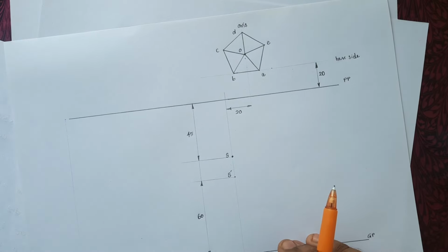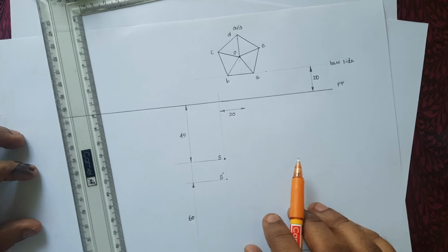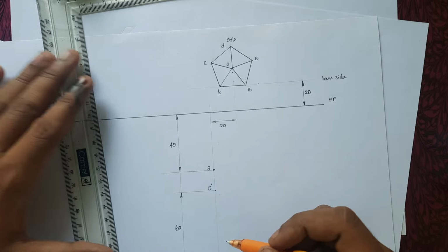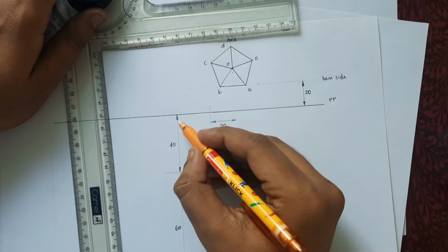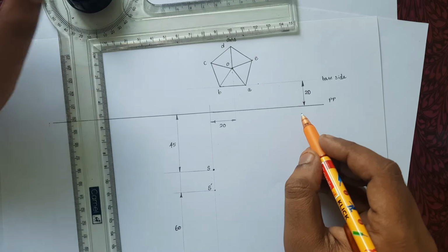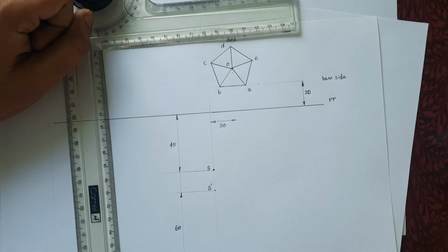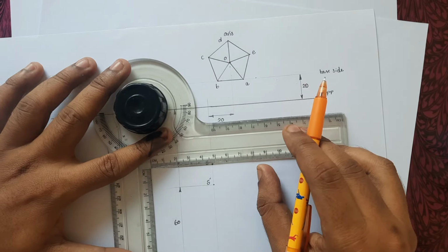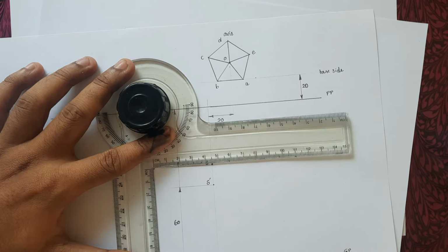Okay, clear. And now we have drawn the top view, and next we are going to draw the side view. So this is the PP, and we need to draw another picture plane. So here this is a station point, right? This is a station point 45 mm from picture plane. We have drawn one picture plane, that is 45 mm from station point. And then we need to draw another picture plane which is perpendicular. That should be also 45 mm from the station point. So here is a 45 mm point.